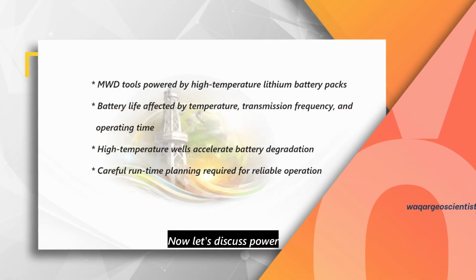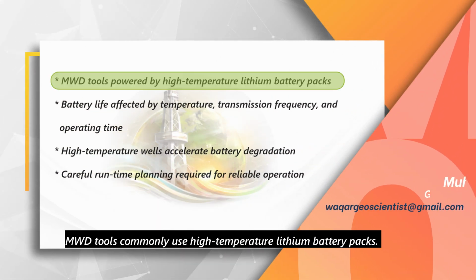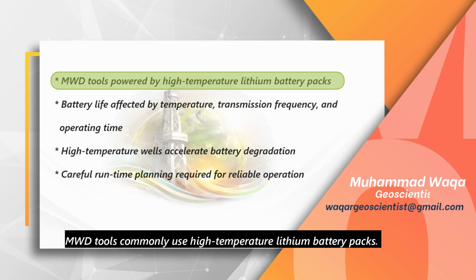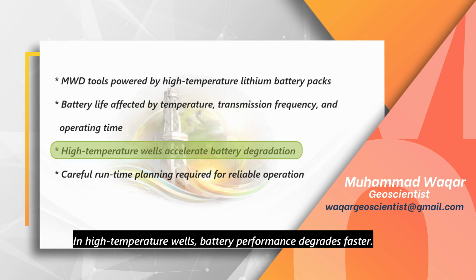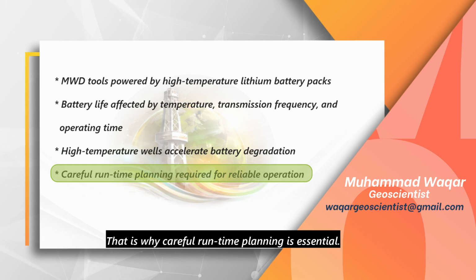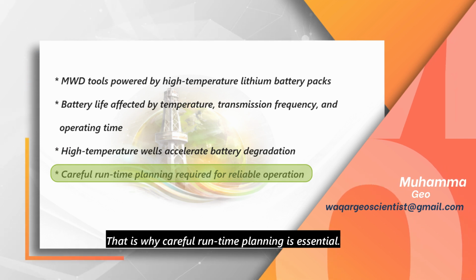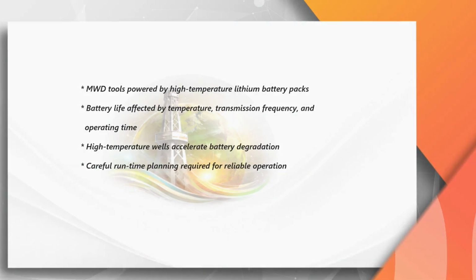Now let's discuss power. MWD tools commonly use high temperature lithium battery packs. Battery life depends on temperature, transmission frequency, and operational hours. In high temperature wells, battery performance degrades faster. That is why careful runtime planning is essential.